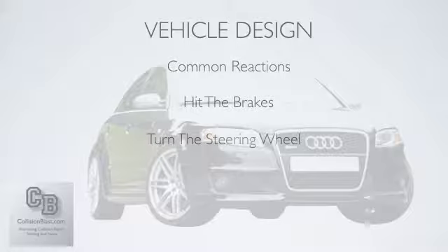And as the collision continues, the momentum continues to collapse. It's going to cause the unibody to mash, which is going to shorten the frame wherever the point of impact is. And then, of course, if it's hit hard enough, you could get into diamond and twist. But now, these are some things to look for.